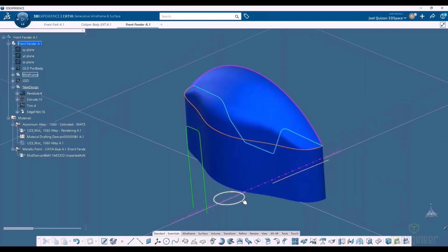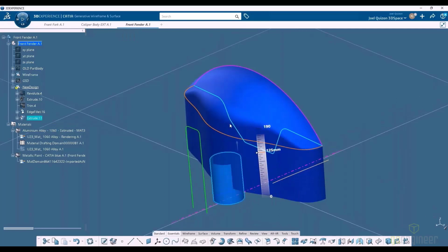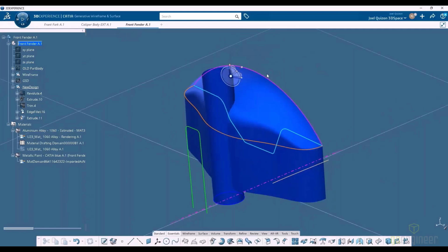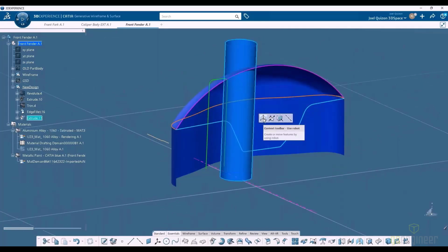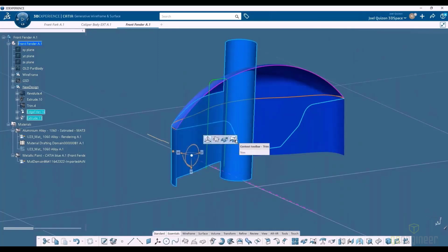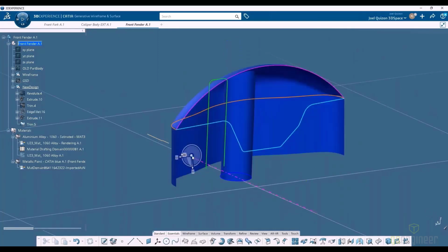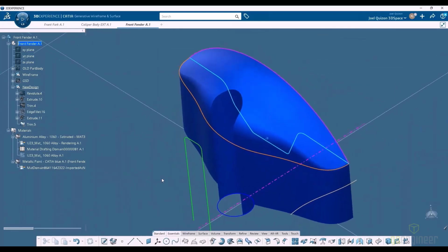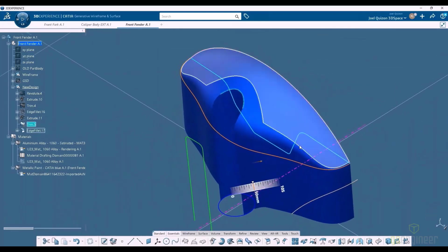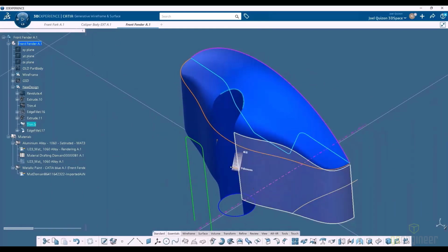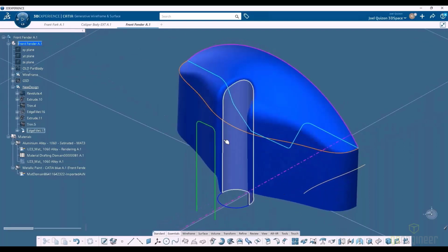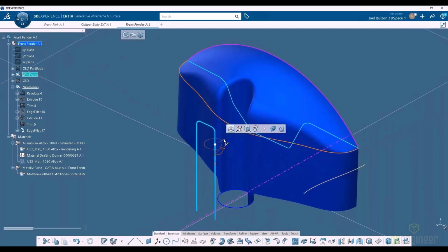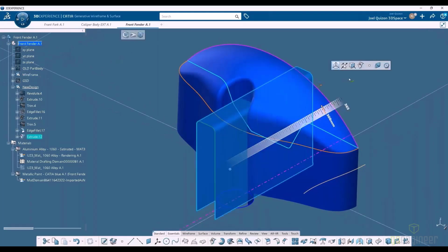There you go. Grab this one, continue to just build this fender here. This time I'm going to trim using this, and I'm picking the geometry that I want to keep. And then I'm dragging it to that as well. So quickly do that. And let's just go ahead and add a quick fillet. There we go. Let's finish this up by just cutting off a few more. I'm just going to continue to do these functions.